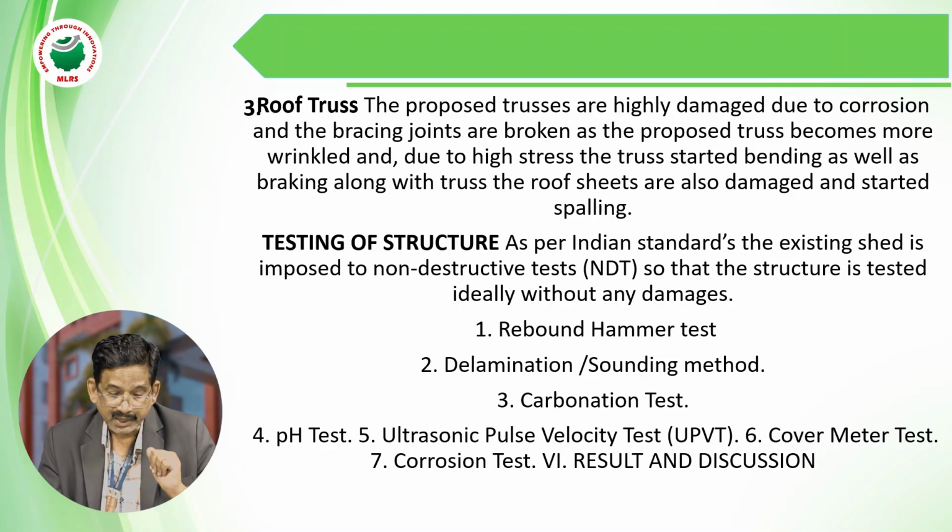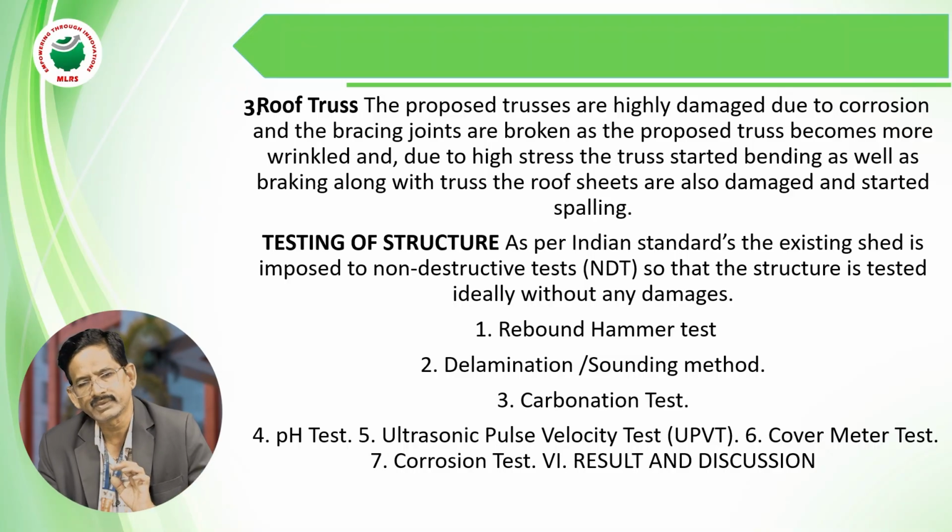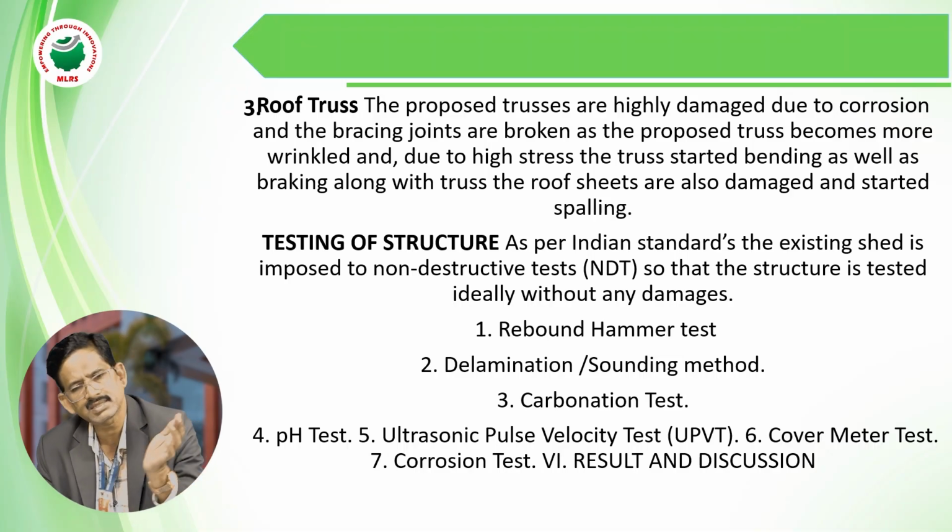First one is the rebound hammer test. Second one is the delamination sounding method. Third one is the carbonation method. Then the pH test, ultrasonic pulse velocity test, cover meter test, and corrosion test. These are the tests we are going to do. In the case study, they followed these tests, but all of these tests are not necessary.